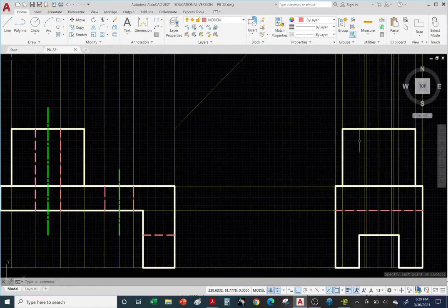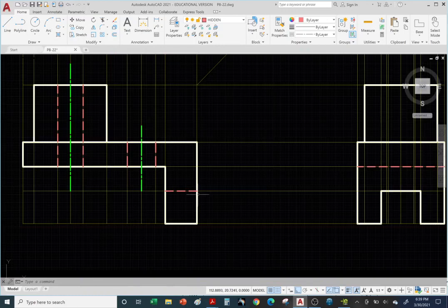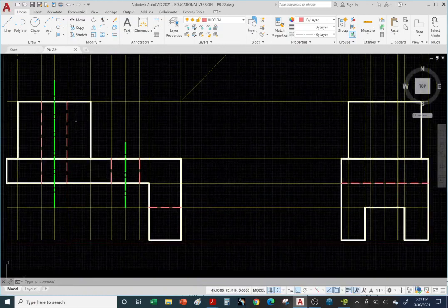Now, instead of having to draw the red hidden lines and center line, going across, hit the 45 and go straight down. See, that's the safe way of doing it. But I'm going to cheat and use the ones that we have here. It's the same holes that we're going to represent in the side view. So we're going to represent these hidden lines for the hole and its center mark.